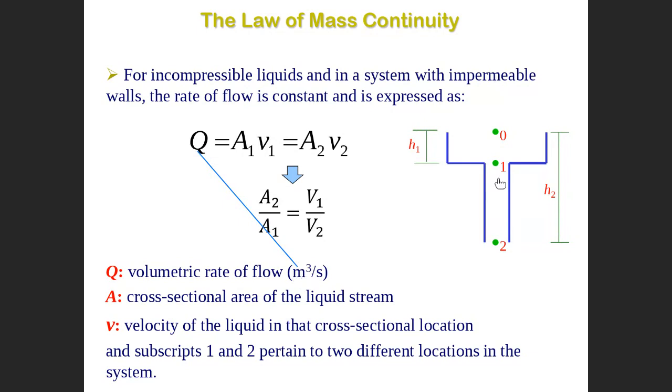Then we can apply the flow rate here, so the flow rate will come at a constant flow rate. When you apply a constant flow rate at a certain area, the velocity will satisfy the condition of avoiding aspiration. Do you get it? So this is the usual approach. Even this is available in software. We call it Magma software. This software helps people do the casting process, doing what I'm just telling you now,